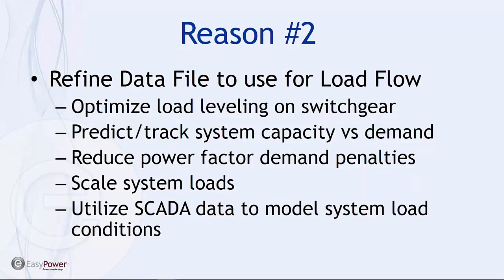Once we have our data file refined to match our actual physical system, and we're using a load flow analysis on a periodic basis, this gives us more capability to optimize my system in terms of understanding what my load capacities are at any particular time, what our ability is to expand or deal with increased demand. We have the ability to discuss with engineering resources what our options are in case we have power factor penalty issues.